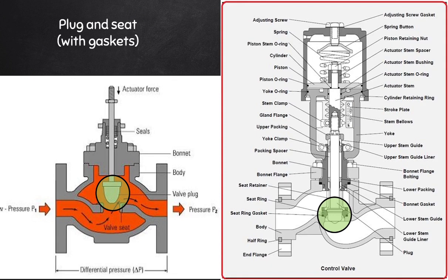Now, typically compressed air is used to activate the valve pneumatically. Note, however, that during a loss in pneumatic pressure, the control valve can be designed to fail either in its fully open position or its fully closed position, and this will depend on the process and what is required to ensure safety during events like power outages or when something goes wrong.